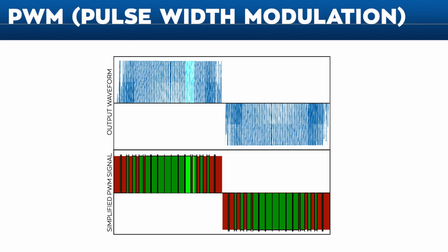After reaching the peak, we then start to reduce the on time until the 0 point, when another IGBT starts to turn on to create the inverted wave. You will notice that the voltage waveform is almost square, but is happening in the positive and negative regions. And that's because the IGBTs are pulling from the constant DC bus.